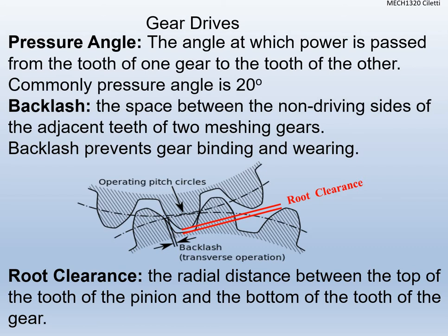When you have too much backlash, there's a big space there. Your gears will most likely not even turn, because they won't even touch each other. They won't even be able to mesh. If you have too little backlash, the gears are going to lock up because they're going to get stuck on one another. Sorry, hopefully that clears it up. What I just said is how I want you to understand and interpret that piece.